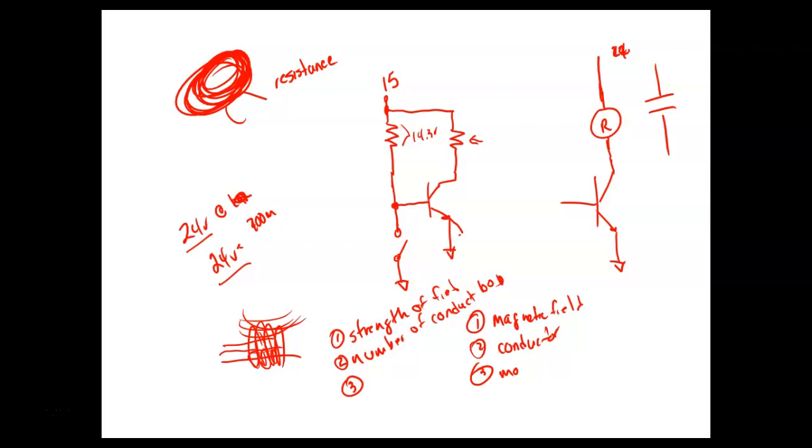Well, the problem is that would blow my relay up. I mean, not my relay, my transistor, because what we just exceeded was the collector-to-emitter voltage with this thing open. The 2N3904 is only rated at 60 volts. So that relay discharges and outputs 90 volts, the transistor can only block 60 volts, and you just blew your transistor. So anytime on a saturated switch you use an inductive load like a relay, you're going to have to put a diode across it right here, and we'll reverse bias it.